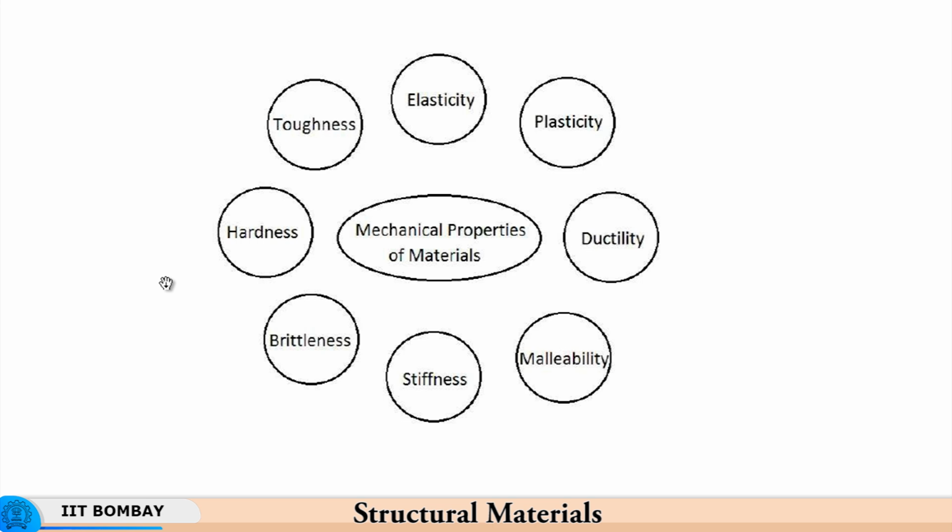Whereas toughness means you need to supply a sufficiently large amount of energy before the product can break, which means that the ductile materials, malleable materials, are able to take a large amount of energy before they break into two. So they permanently change in shape as in plasticity. You apply more and more load, more and more permanent deformation to it, but it absorbs this so-called energy, and therefore it.